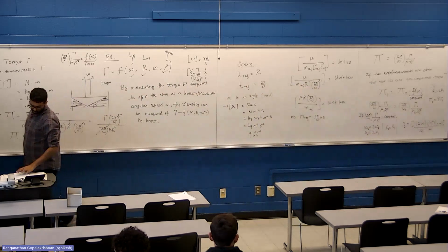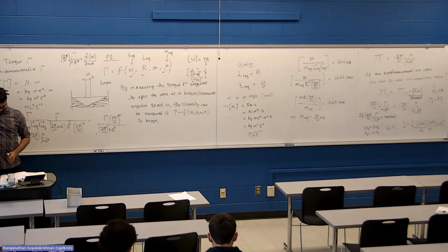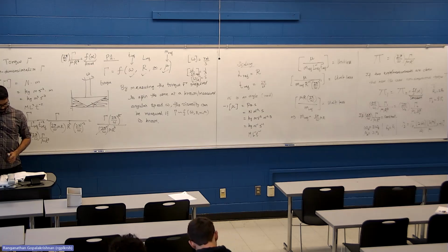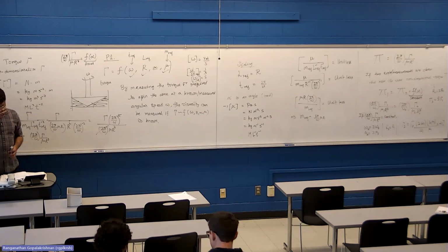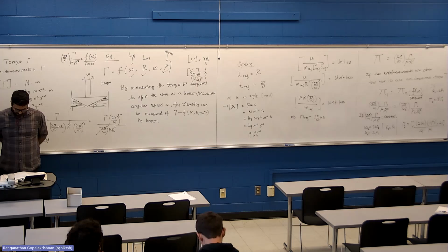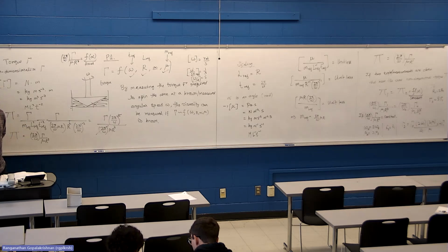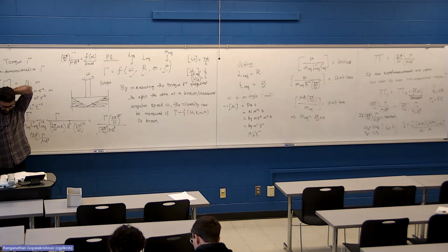Okay. All right, problem 2. A student drops two spherical balls of different diameters and different densities. She has a stroboscopic photograph showing the position of each ball as a function of time. However, she wants to express the velocity of each as a function of time in dimensionless form. Develop the dimensionless group. The equation of motion for each ball is given, where m is mass, cd is drag coefficient, a is area, v is velocity, t is time, and rho is density of air.